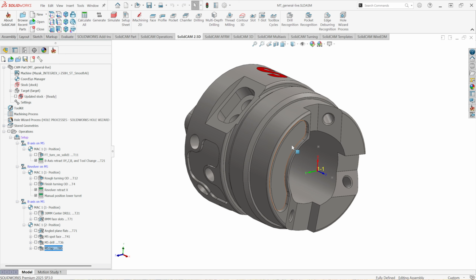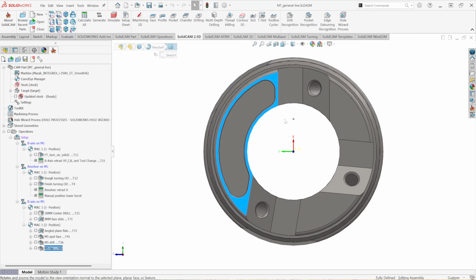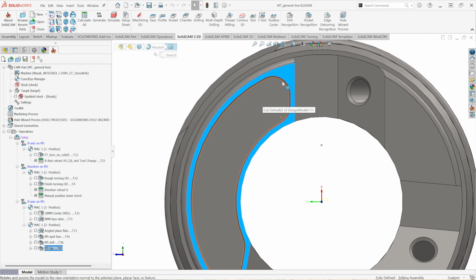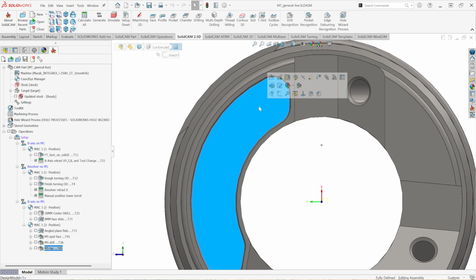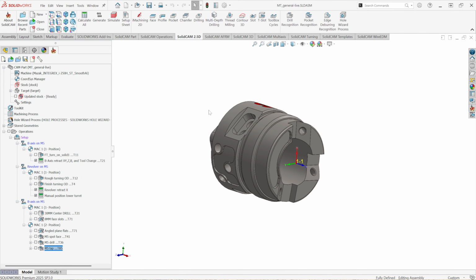In this video, we're going to be focusing on the last of the facing operations, or the operations on the face of the part, which is going to be this pocket. If I look down normal to this face, we're going to see that we have a pocket, but then we also have some tapered walls on the periphery of the pocket. So we're going to do this in two different operations, one that addresses the bulk material coming out, and the other one in the next video to deal with the 5-axis motion on the outside of that pocket.